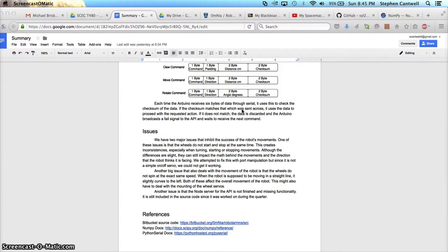And also, writing to the servos is done in such a way that you need to write to one servo first. So if we were moving forward, you'd have to write to the left and then the right, or the right first and then the left. But either way, one servo would start just a little bit ahead of time, and that would throw off the distance, especially if it was going a longer distance. So the vectors that you give it, don't be surprised if it doesn't land exactly where it should.